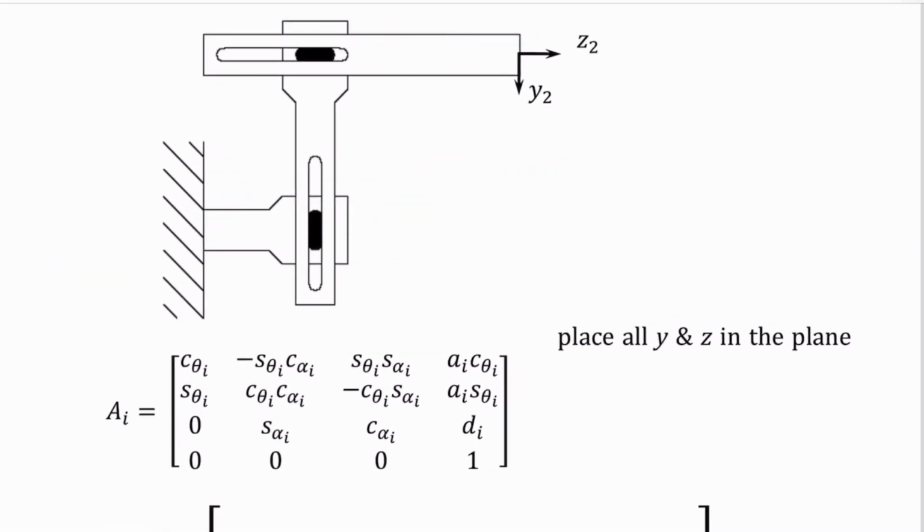My final problem is a 2-joint Cartesian robot. And so I've got to first draw in where my z-axes are. And so my prismatic direction of movement is along here. So I'm going to call that my z1. And then I've got another prismatic joint here. I'm going to call that my Z0. I can locate my base frame anywhere along here. Makes sense to put that origin right at that start. So any distance I move from here is my D value.